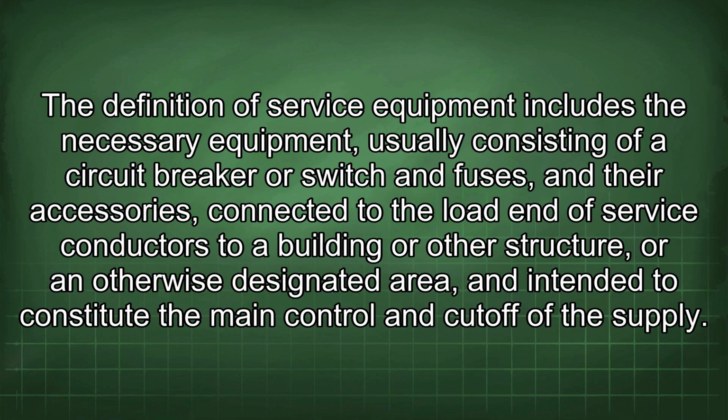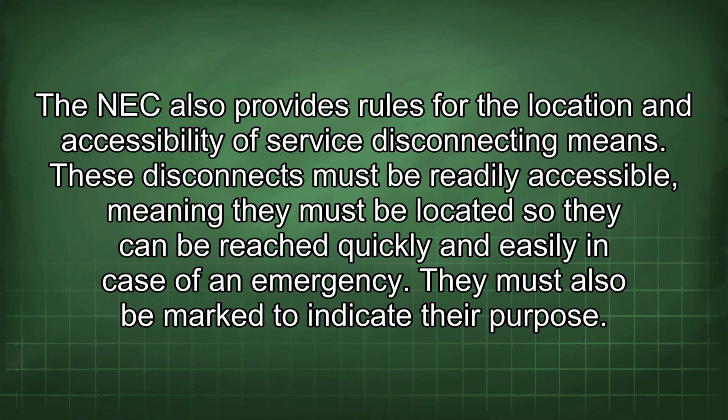The definition of service equipment includes the necessary equipment, usually consisting of a circuit breaker or switch and fuses, and their accessories connected to the load end of service conductors to a building or other structure, or an otherwise designated area, and intended to constitute the main control and cutoff of the supply. The NEC also provides rules for the location and accessibility of service disconnecting means. These disconnects must be readily accessible, meaning they must be located so they can be reached quickly and easily in case of an emergency. They must also be marked to indicate their purpose.